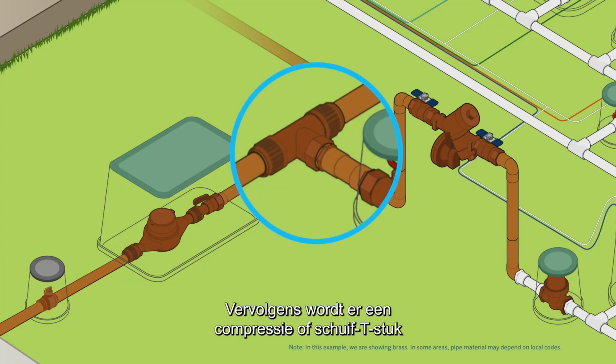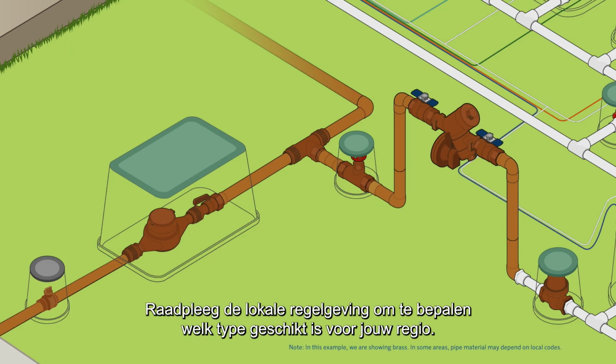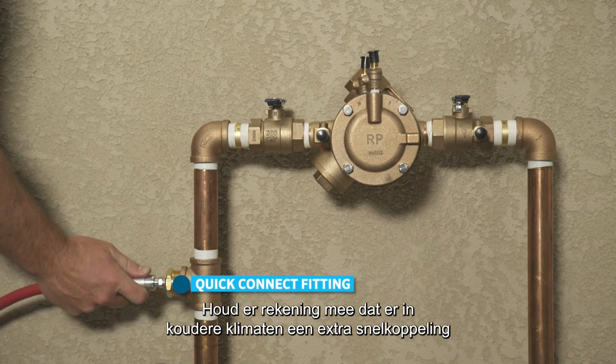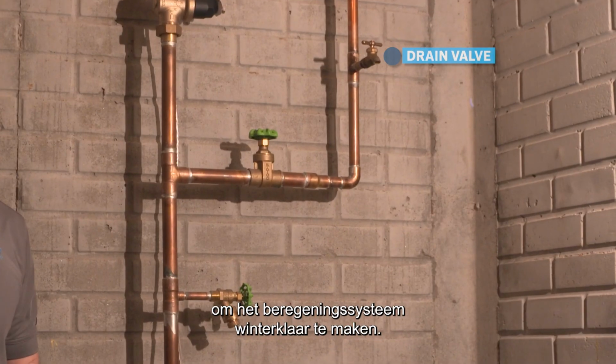At this point, a compression or slip tee is installed at the POC. The tee can be made of various materials. Check your local codes for the appropriate type used in your area. Note that in cold weather climates, an additional quick connect type fitting and drain valve should be added to the point of connection for winterizing the irrigation system.